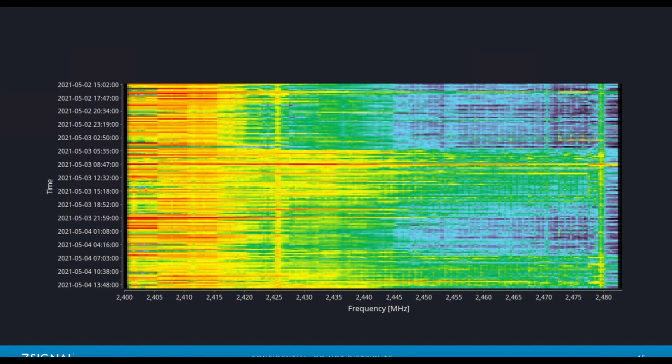All right, let's move on to our next one on 2.4. As you can see here, this is just a big, big mess, rendering channel 1 and channel 6 almost unusable. This is just another great example of a spectrum chart that looks awful. Again, you've got to go back to your 3 columns, and that's your guide. That's your baseline: your 3 columns, 1, 6, and 11. If you don't see anything that even comes close to resembling that, you're in big trouble. Yeah, if your primary application in 2.4 gigahertz is Bluetooth, then you're looking pretty good. But if it's Wi-Fi, you've got some challenges.